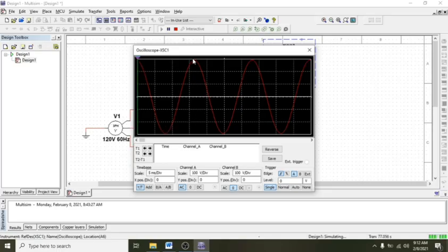So to identify which one is, okay, so to identify which one is, by the way, you need to click this, no? So AC. Okay, so to identify which one is for channel A, you can choose to display only channel A. Okay, so by clicking 0, as you can see this waveform is for channel A, and then of course the smaller one is for channel B.